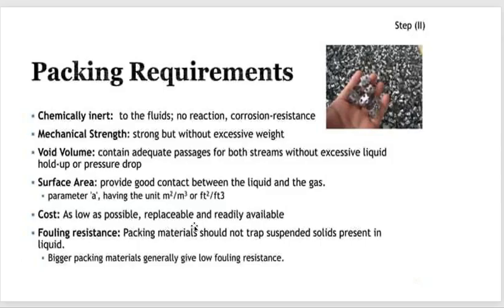Okay, so now we make a little comparison between when to choose packing and when to choose the tray tower. Okay, packing requirement: it should be chemically inert and corrosion resistant. When you choose the packing, you should remark and consider that the packing material should be inert, not to react chemically with the vapor or the liquid. Okay, and also the mechanical strength.